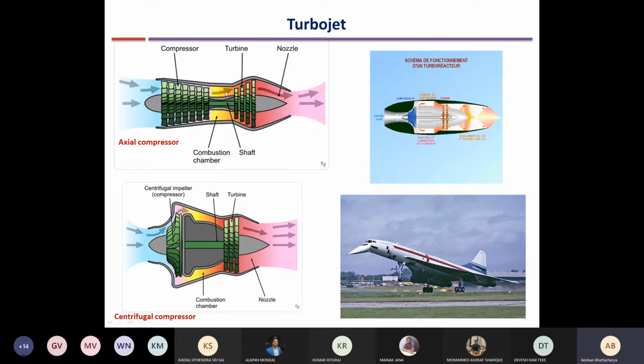So for gas turbines, typically combustion is very good. Almost 99% of the energy that is in the fuel is released as useful energy. The fuel almost gets fully combusted because of the very low fuel air ratio that is used, or very high air fuel ratio. Means the amount of air used is very high. You have a very lean mixture, so almost the entire fuel is burned up.